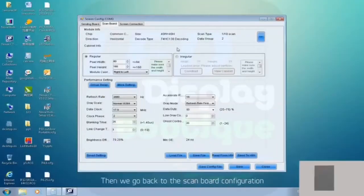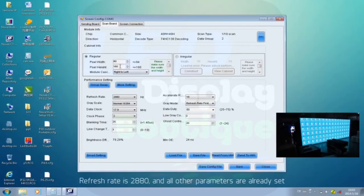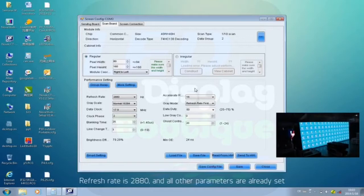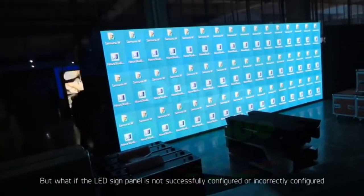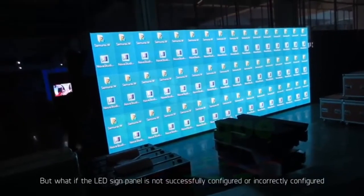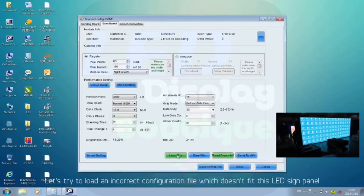Then we go back to the scan board configuration. You can see the parameters here. Pixel width is 80, pixel height is 160, refresh rate is 2880, and all other parameters are already set. So each LED sign panel is showing the normal image duplicated from the computer. But what if the LED sign panel is not successfully configured or incorrectly configured? Let's try to load an incorrect configuration file which doesn't fit this LED sign panel and see how it goes.